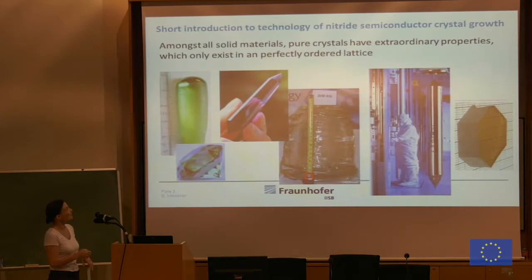And here you can see all these man-made crystals. They are all artificial crystals. It's not what you can find in nature. But you see that they can have different sizes. They can have a very large size, like the silicon crystal. They can have facets. They can have no facets. But the idea of growing a crystal is to give it not a natural shape, but, let's say, a round shape or some shape that helps us to slice the crystal into the usable shape that we want, which for the electronic cases is a wafer, which is a round sheet.